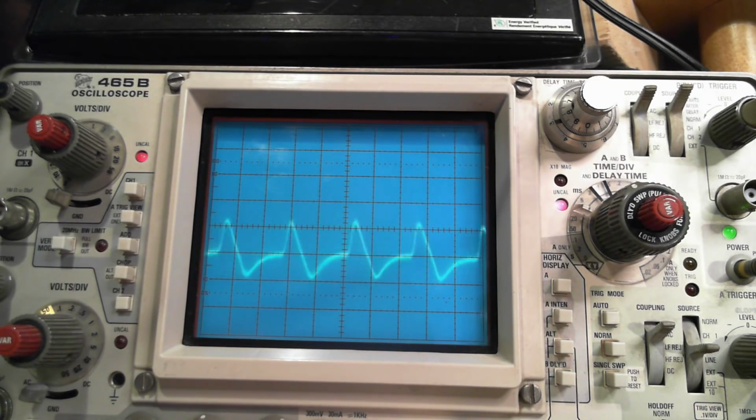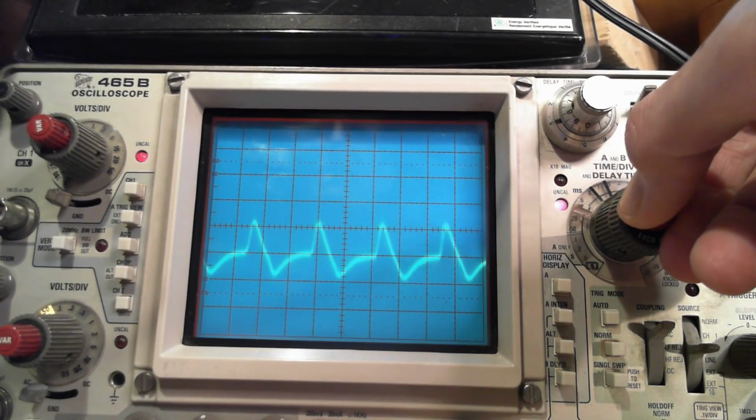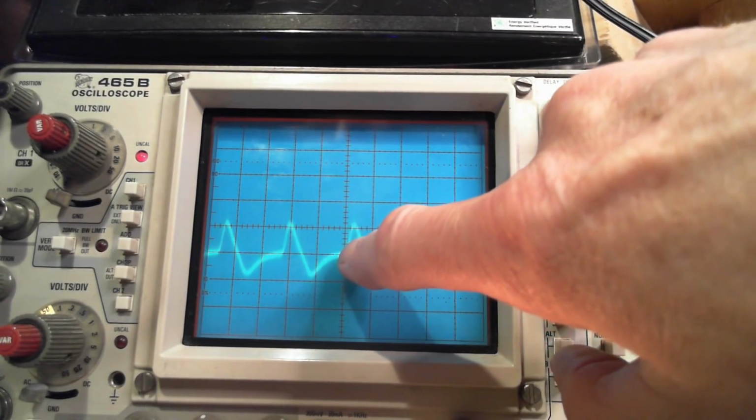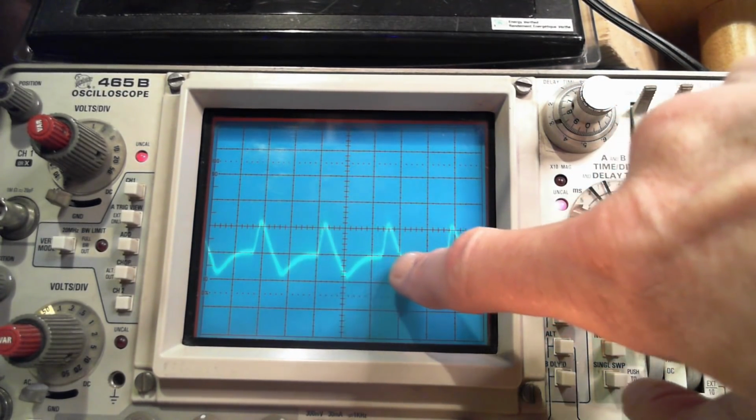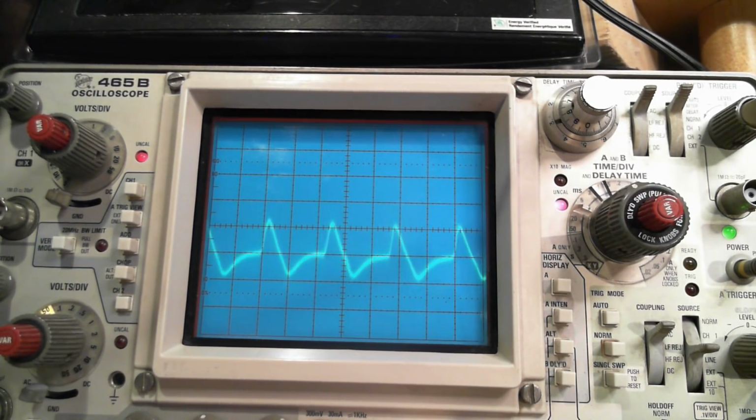When the signal is quite weak, it actually sounds much more like it should. It looks more like it should, but it's still distorted. Now if I can only stop this, just see if I can fool it into stopping here. So see that sharp corner right there? To generate that sharp corner requires a lot of harmonics. That's probably much of what we're hearing in terms of the harmonics. Okay, I can't look at that and tell you what's wrong with this receiver just from looking at that.